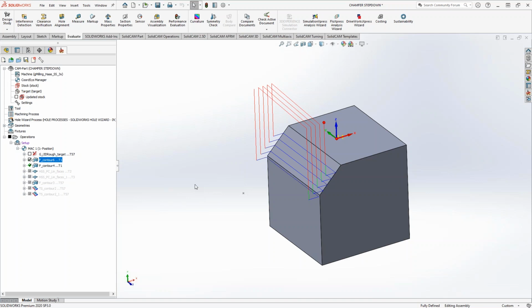But this part right here is just using the profile toolpath for chamfering with a little bit of a step down on an angle. But let's say, for instance, there's something about this toolpath that I just don't like, and I'm not finding an option inside the toolpath to really regulate that. I want to go in there and maybe change a data point, relink something. And if I can't find the option inside the toolpath, here's another avenue to go and edit that toolpath.